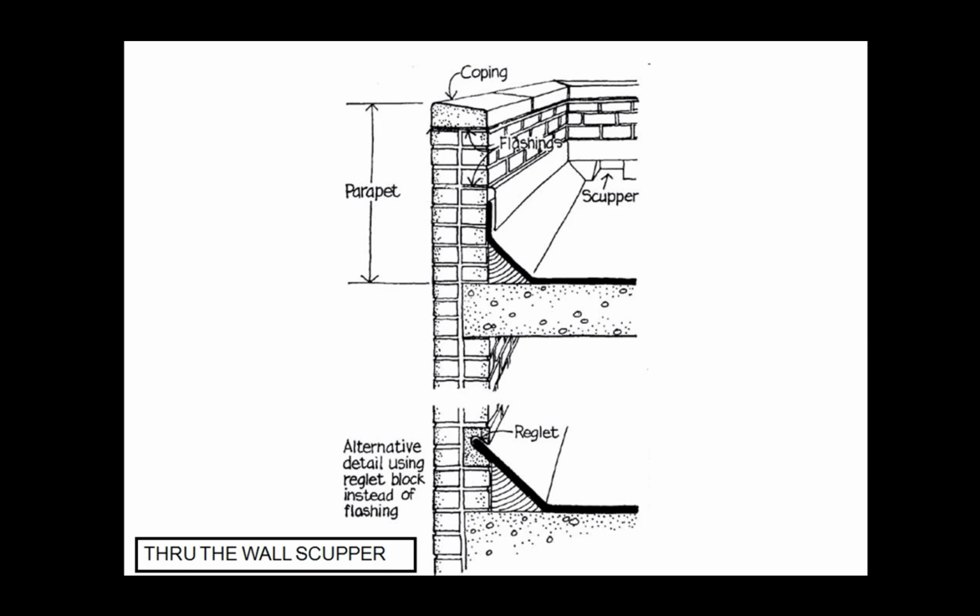All right, so basically all of that area is waterproof between using the flashings and the cement and concrete material between your bricks, so that any water that hits there drains down the side onto the roof. You see that sloped area. It could have a triangular wood block behind it that brings the roofing material up, and then the flashing over that ties into the parapet and overlaps it to create that watertight bond, and guides the water down onto the roof.